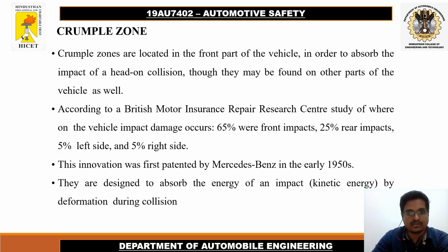According to a British Motor Insurance Repair Research Centre study of where on the vehicle impact damage occurs, 65% were front impacts, 25% were rear impacts, and 5% on the left and right sides respectively. This innovation was first patented by Mercedes-Benz in the early 1950s. They are designed to absorb the energy of an impact, especially kinetic energy, by deformation during collision.